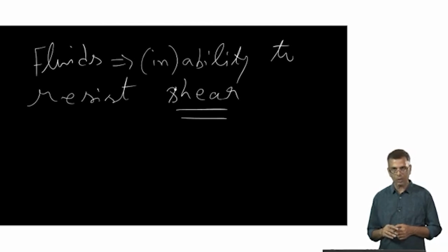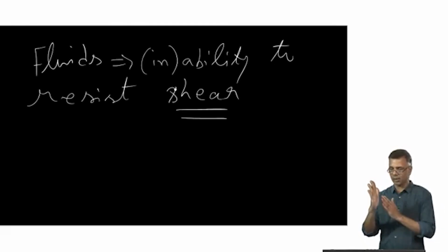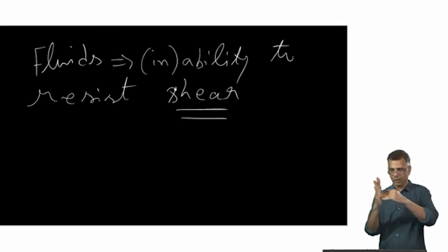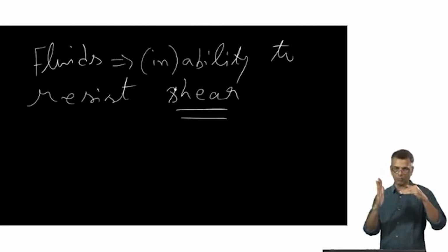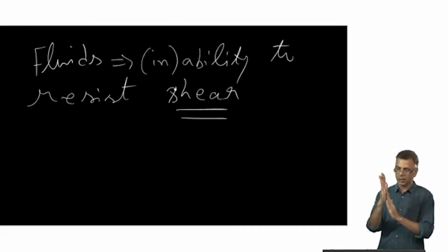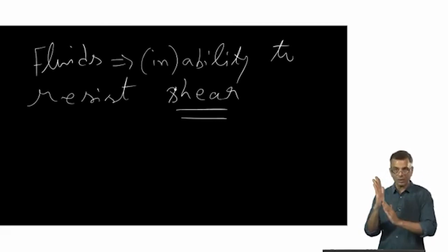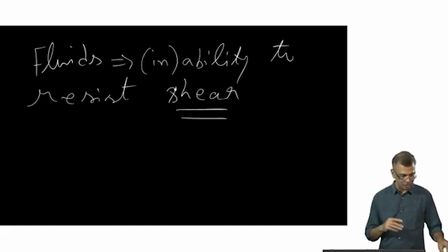Essentially, you think of a surface, and there are two kinds of stresses, two kinds of force per unit area you can think of. One is a normal force: there's the area element, so the normal is like so, and you are applying a normal force. The other kind of force you can think about is when the force is tangential to the surface element, like so or like so, and these are called shear stresses. This is called a normal stress, and this or that is called a shear stress.